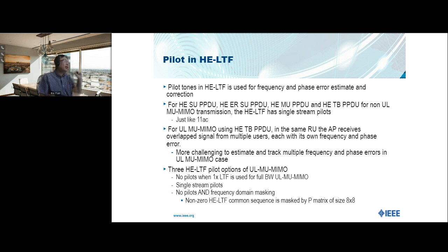Or you can use a frequency domain mask. Basically, you have no pilots, but use a kind of frequency domain mask to separate the channels of different users and do channel estimation. This way is less likely to be used and not any products use it, so we will not go into the detail of it. Okay, most products, if you use it, will probably use the first one.